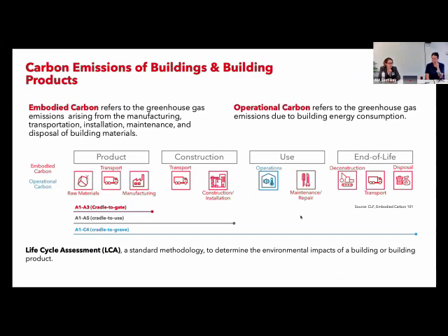So ultimately, the fabrication is still in. And again, we typically are documenting this in an A1 to A3. I think maybe where the question, if I could reframe slightly, would be, do all instances take into account how much carbon is really handled with on-site fabrication? Right now, that isn't always captured. Typically, what we as architects and engineers can document ends up being an A1 to A3 that we pass. Sometimes we try to catch that A5 scope of what really is on-site construction and fabrication.